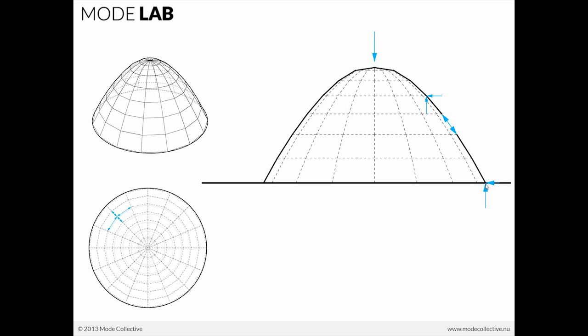Which means that where we had just an anchor before and an internal force, we now have to work with an external force. This is probably going to be coming from gravity, where the grid shell has to resist gravity by allowing a compression force to move through the section of the grid shell. So there are both ring and meridian forces that pass through the surface of a grid shell. In the case of what we had as an example for the tension system, those were also similar. Those would also be the same terms for the forces that are traveling in the different directions.